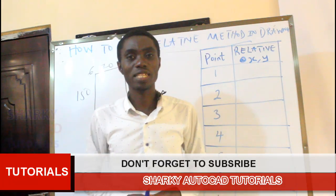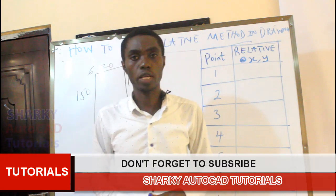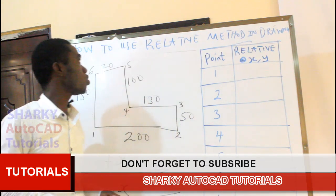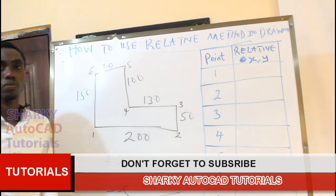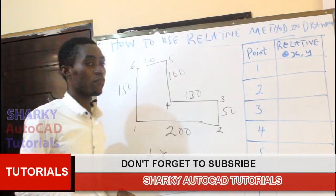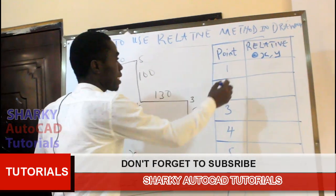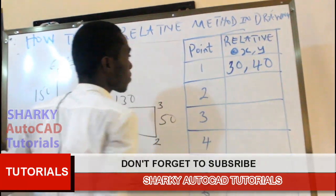In our previous lesson, we used the absolute method in drawing the shape as you can see on the board. Today, I'll show you how to use the relative method in drawing the same shape. Now, in relative, the first thing for you to do is to bring the @ symbol throughout. Don't forget our starting point is 30, 40.